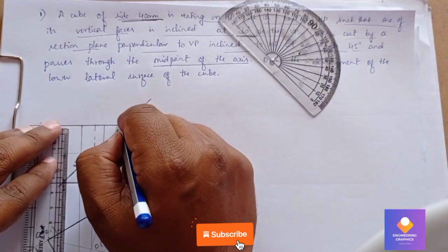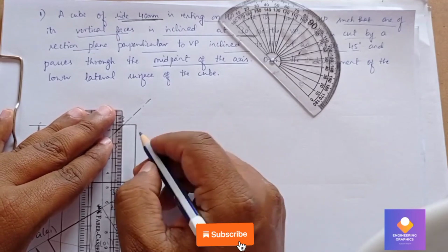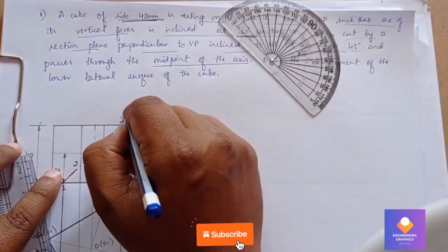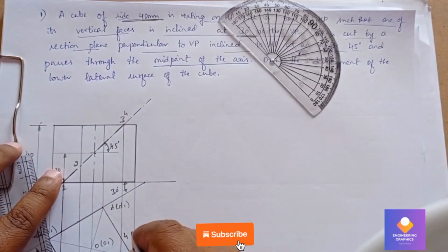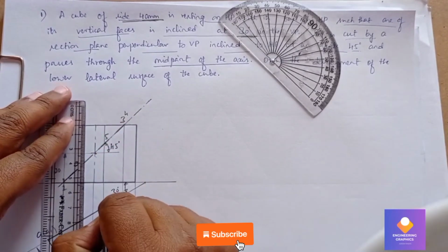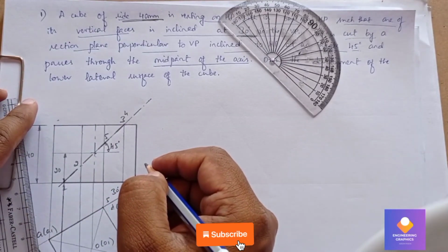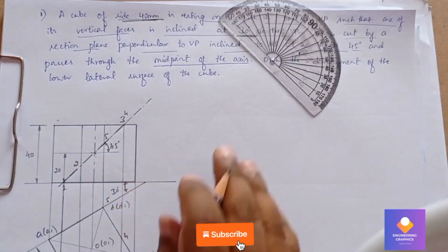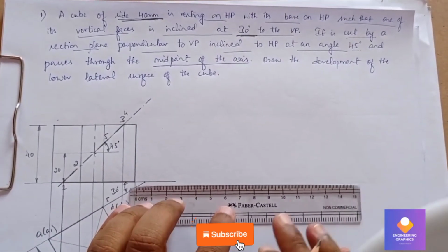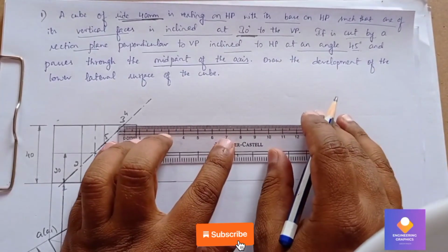Same way we need to write 3 here. So 3 here is cutting on the BC. That is the point 3, and then we have point 4 here, and then point 5 we are getting on the D only. So we write D here also. So the marking of the points we have done. Now we have to draw the development of this. So extend the lines.